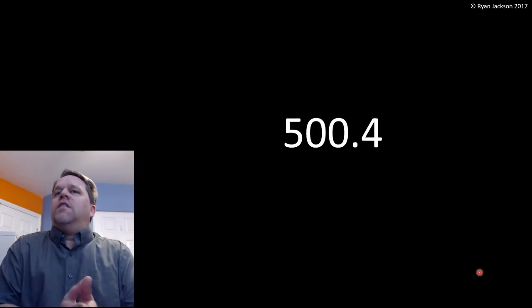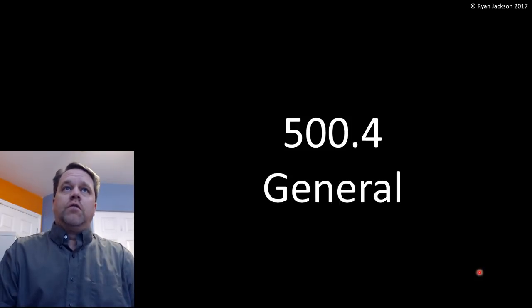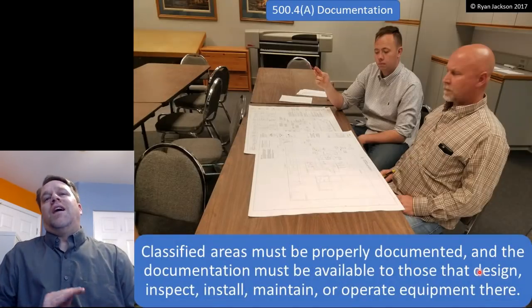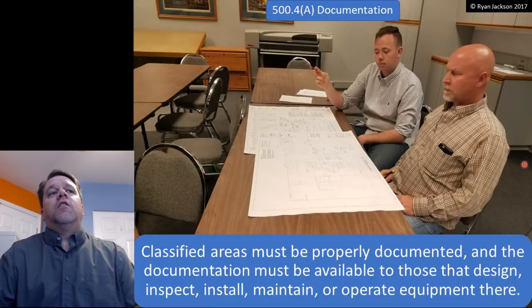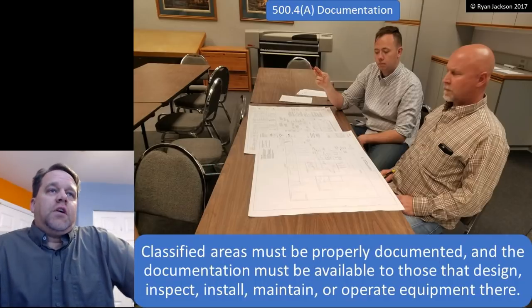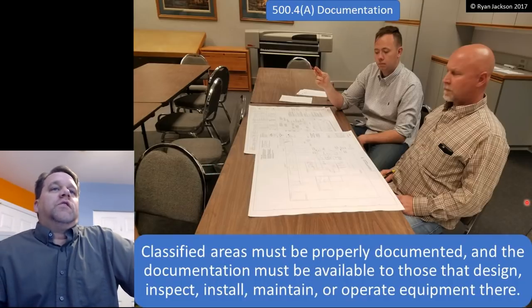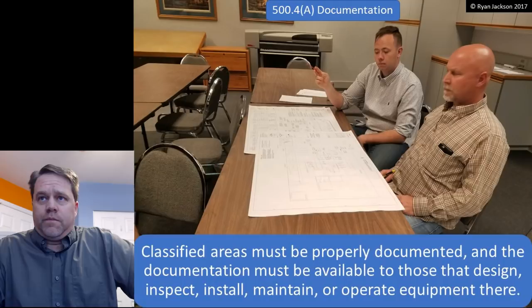500.4. I'm going to start getting into the actual rules here. 500.4, in my opinion, is one of the most critical sections in all of Article 500. General requirements A, documentation. I am a stickler on this requirement. Classified areas have to be properly documented, and that documentation must be made available to those that design, inspect, install, maintain, or operate the equipment in the hazardous location.